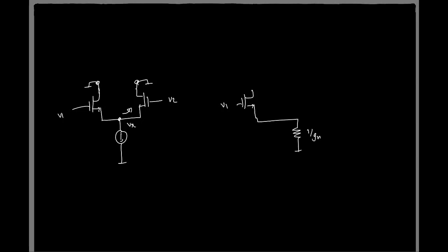So if you see, due to V1, you will have this transistor loaded by a 1 by Gm resistor. But 1 by Gm is less than the R0 is high. I mean, the drain should be at a low impedance. That's what I'm assuming, right? See, if you have this connection, it doesn't depend on R0. What do you call as R0? I mean, output resistance, RDS. Yeah, I already asked you to derive, right?